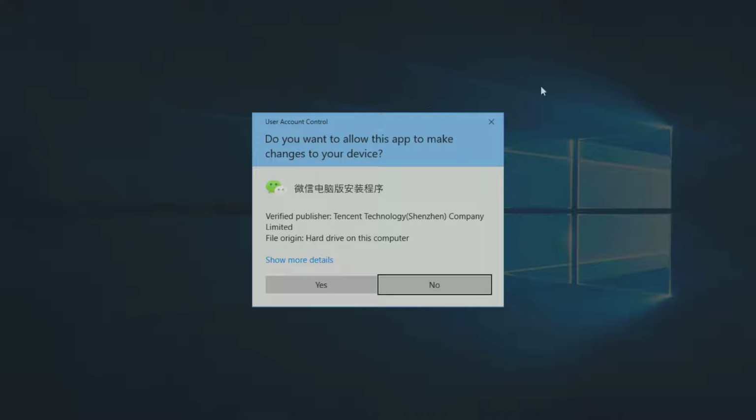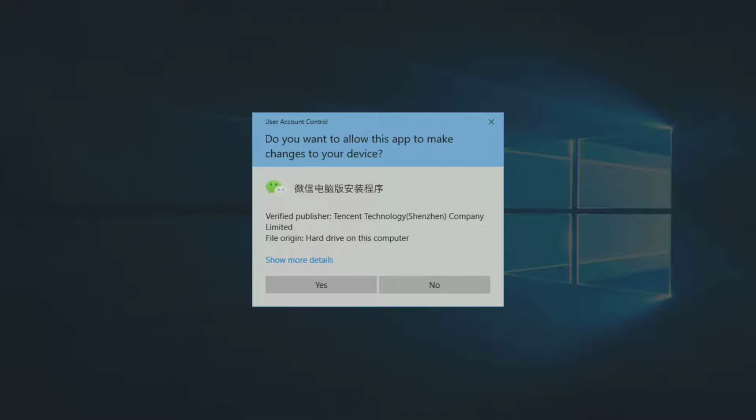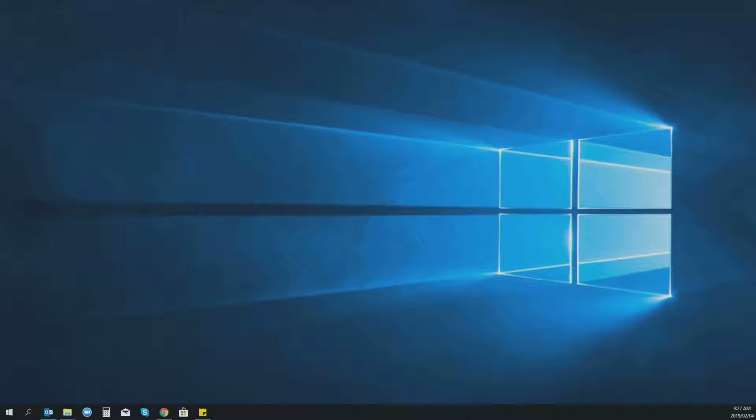Now, an important thing about when the frame synchronizer may be dropping and adding a lot of frames and chopping things in and out, to maintain frequency lock, you don't need to worry about the audio. As I said, the frame sync is really sophisticated. There'll be no pops or clicks to the audio whatsoever, even though we may be dropping frames like crazy. So the audio will go through unmolested and completely clean.